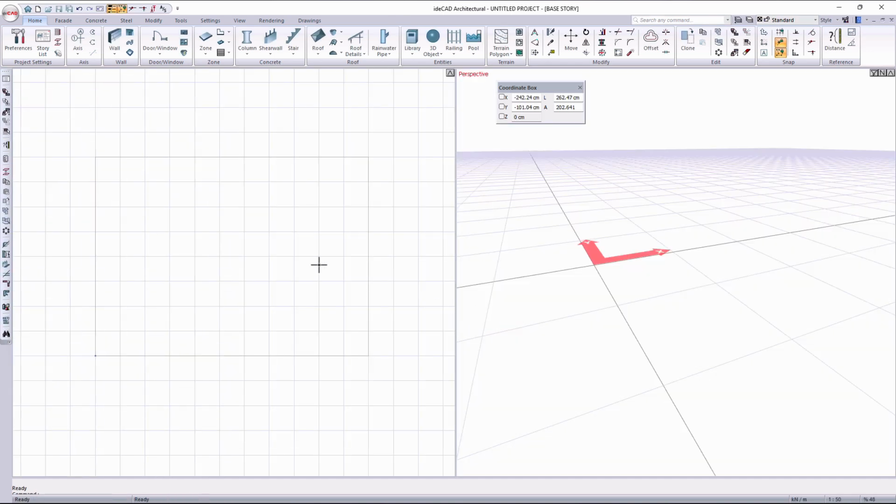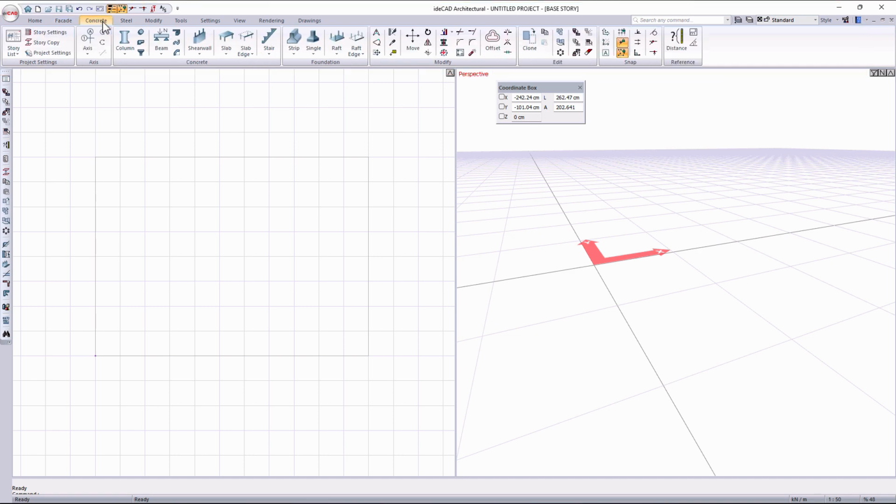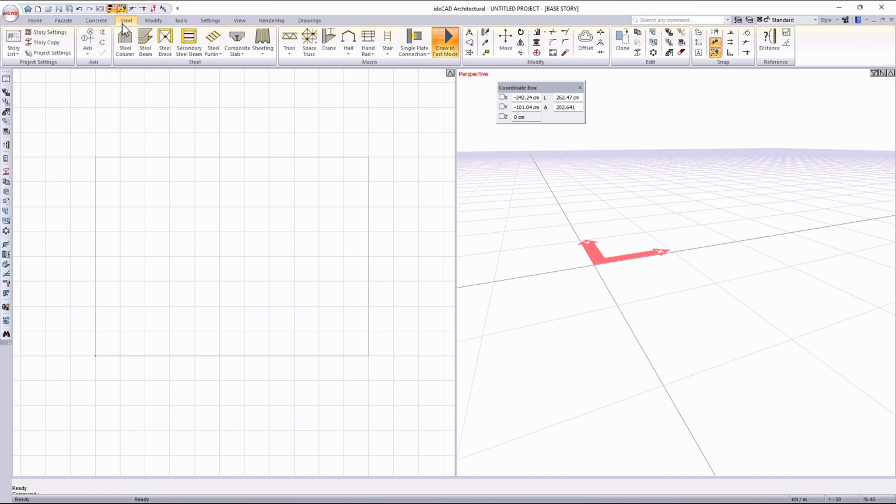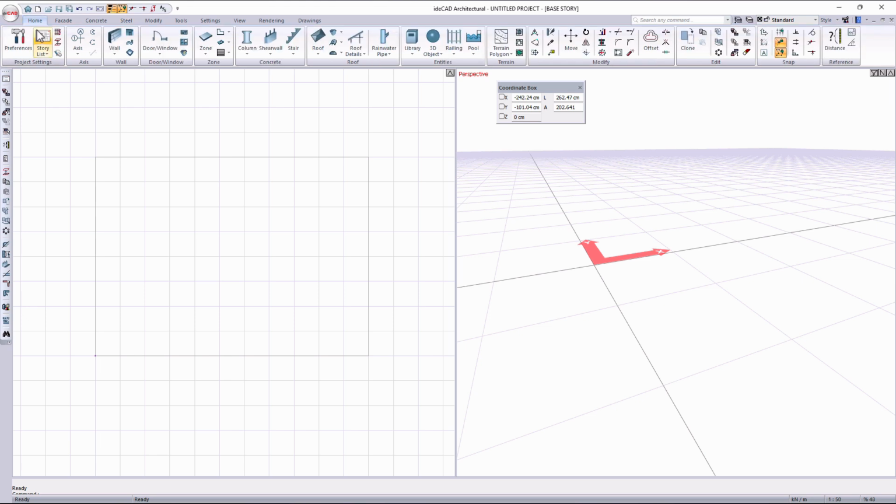When a project is opened, the ribbon interface appears. In this interface, all commands are organized into categories represented by icons. The commands are grouped under 10 tabs according to their purpose of use. The Home tab includes commands for the most frequently used building elements when creating an architectural project, such as axes, walls, doors, windows, and columns. Since IDCAD Architectural works in integration with IDCAD Structural, it also contains commands for elements used in formwork plans, such as columns, beams, and shear walls.